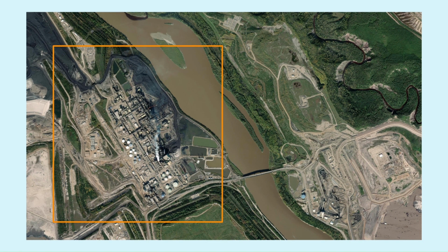Let me explain why we use these custom coordinate systems in general. First, the numbers are smaller. I want you to think back to the 1950s, 1960s, what work was like back then, especially for surveying, construction, a lot of this geospatial work. You didn't have computers, less likely a digital calculator. You didn't have GNSS. A lot of surveying was still done with chains back in those days. So you needed a coordinate system that fit the area that you were working with. That was essentially localized to the area.